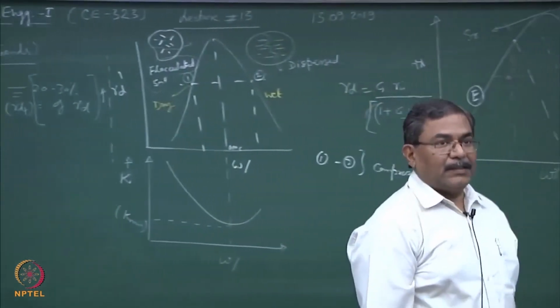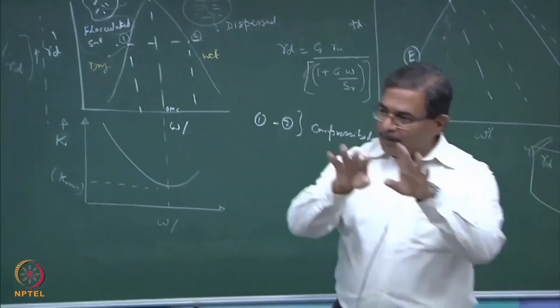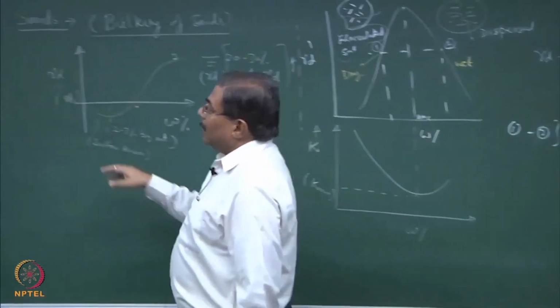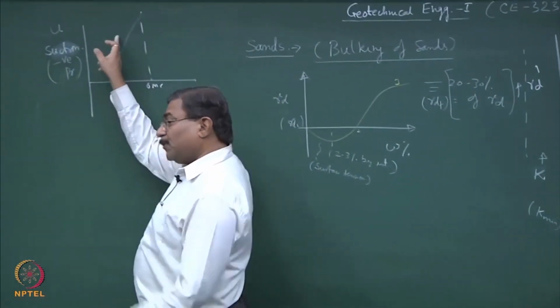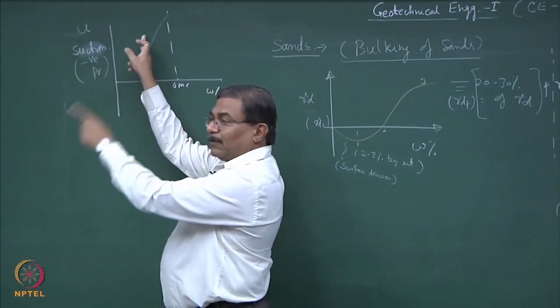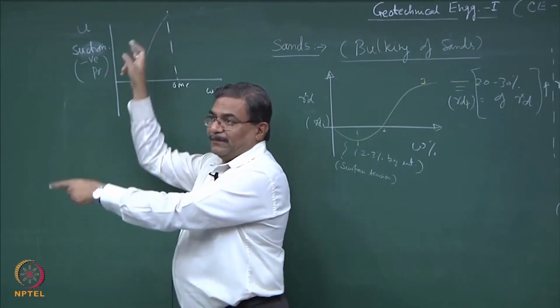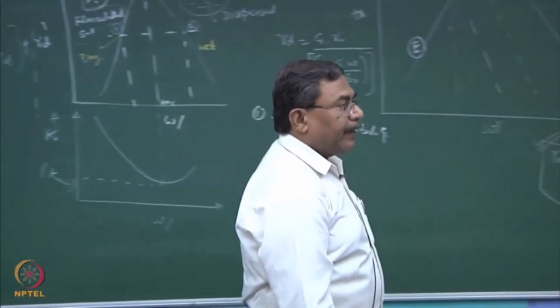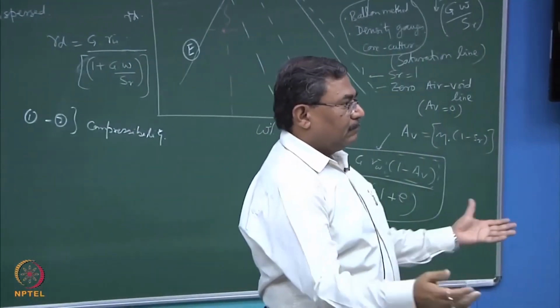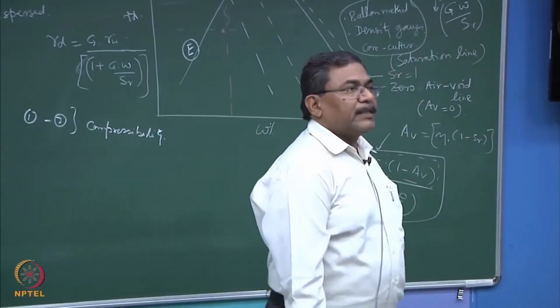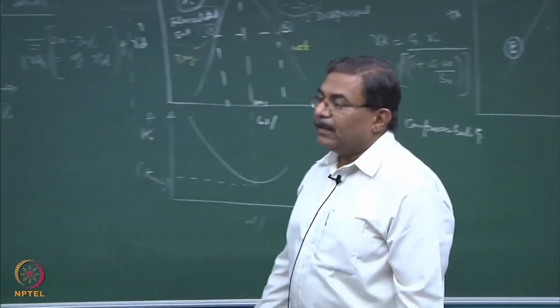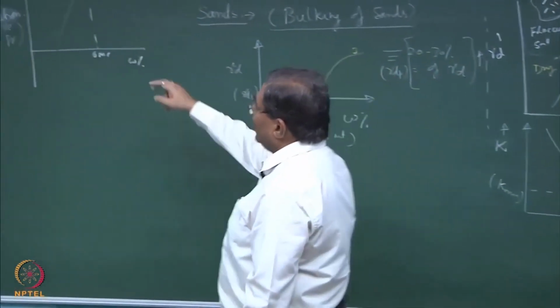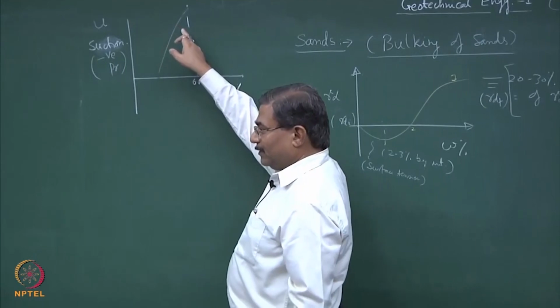Are you realizing this? So, next time when the trains move, what is going to happen? This equal amount of the pore water pressure is going to get developed, and hence your effective stresses are going to decrease. So, it becomes very tricky to operate trains or the infrastructure, vehicular traffic, if you are not taking care of how to compact the soils, clear.